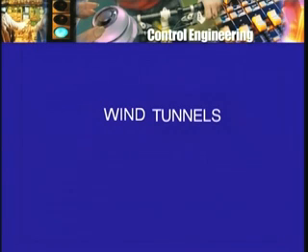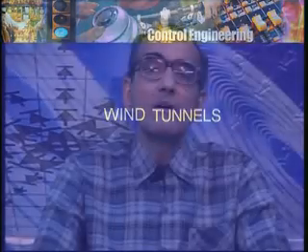And in fact, one may make studies of these smaller models in wind tunnels. For example, wings or wing sections, new designs may be tested in a wind tunnel, and therefore the actual wing that is studied may be much smaller than the wing of the aircraft for which it is being designed.